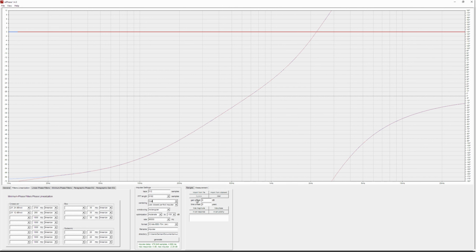So you're flexible here. In fact, even with the miniDSP 2x4 HD, you can use 2048 taps in just one slot, and you can use the remaining 3 channels for the remaining 2048, a total of 4096, I think. And with the Flex, you have 6144 taps. So it depends on the model, but it's always the same format.